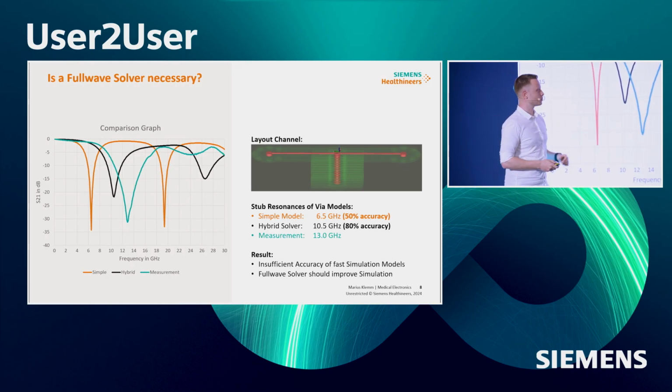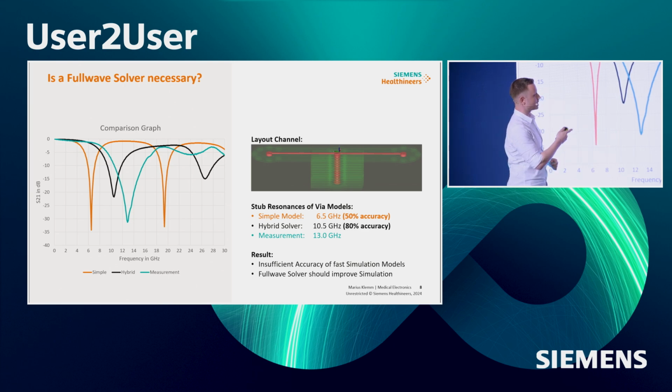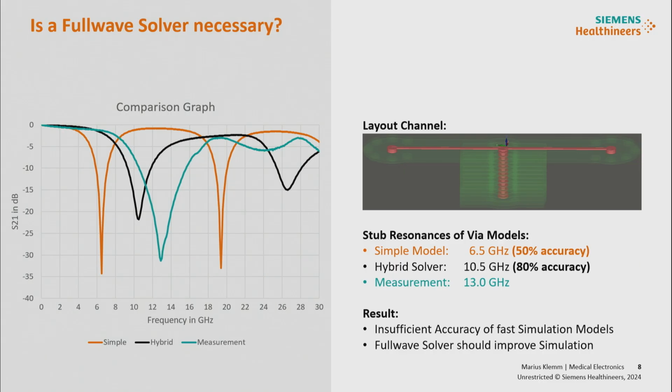All right. This is one example of how to solve this in HyperLynx. This is a channel that I built, which we also had a measurement for. On the left and right, you see the attachments for compression mount connectors, a microstrip connected through it, which was about 1.5 centimeters long, and then a full THT via drilled through it, which represented the entire stub.